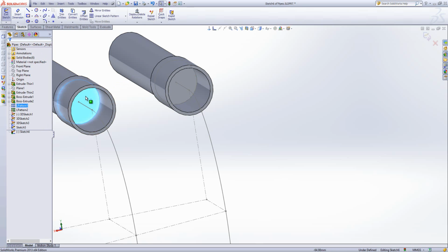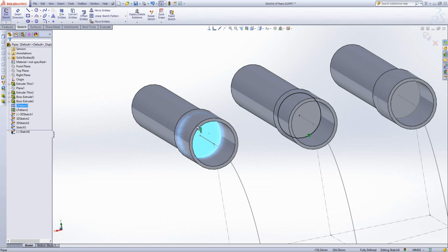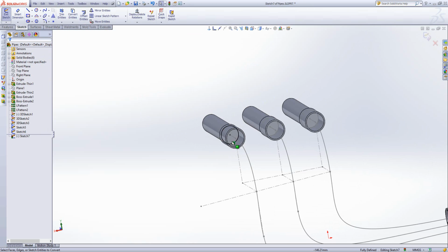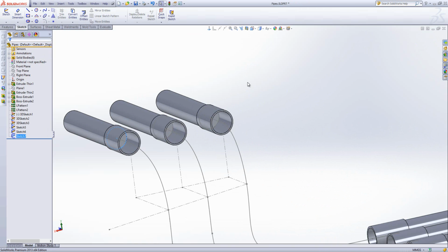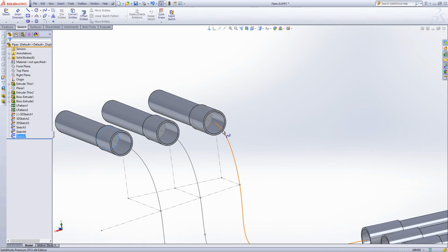I'm just going to go and do the other one. So again, start a sketch on this face. I've already got the face selected, so when I hit Convert Entities, it will automatically take the edge of that face and project it onto my sketch plane, which is coincident with the face. So that's why you don't see any translation in the actual geometry itself. And lastly, let's do a sketch on this face, and again convert entities on that. So that's another reason why I made these lines go up to this face. Obviously for sweeps, the path line here has to be coincident with my actual profile.